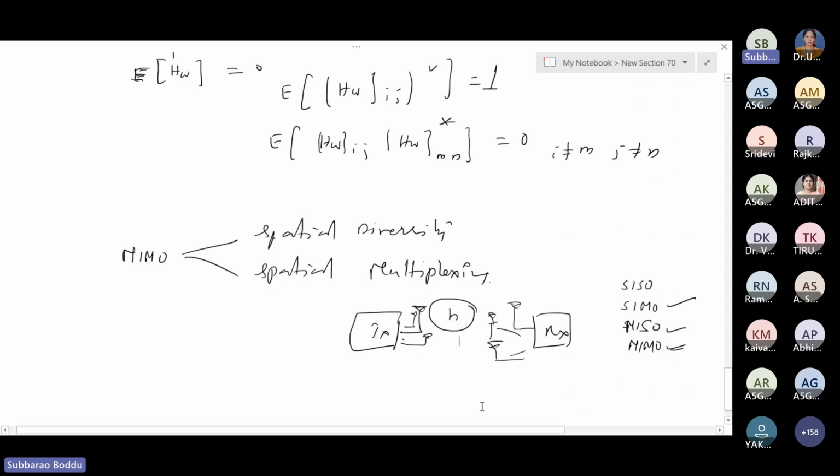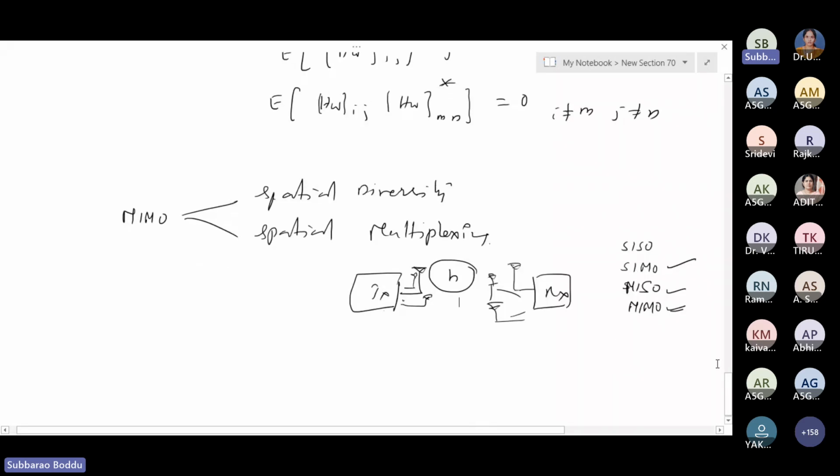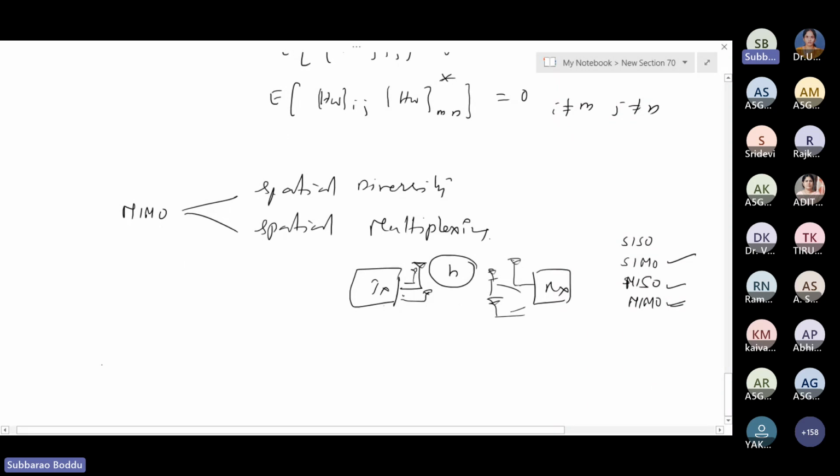Note that here our aim is to get the diversity out of these 4 systems. Once again, in diversity, when you send a signal onto the air, we would like to receive multiple copies at the receiver. That is, in simple terms, diversity. It can usually be obtained in time domain, in frequency domain, and in space domain. We are most interested in space domain, where we defined rich scattering, poor scattering, the coherence distance, and the angular spread.